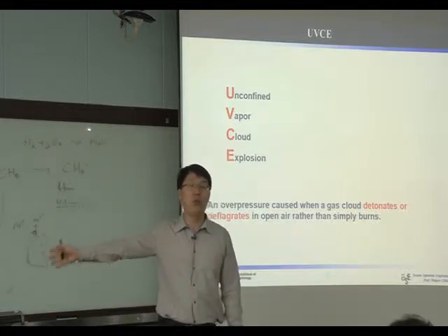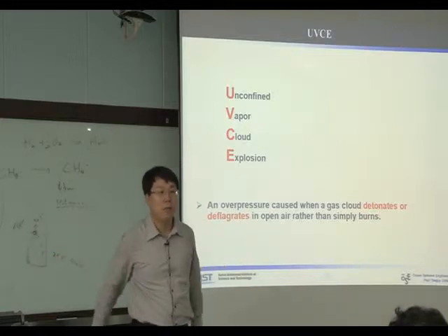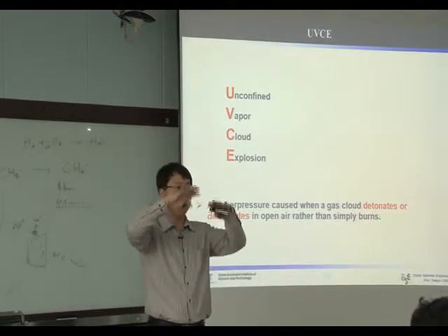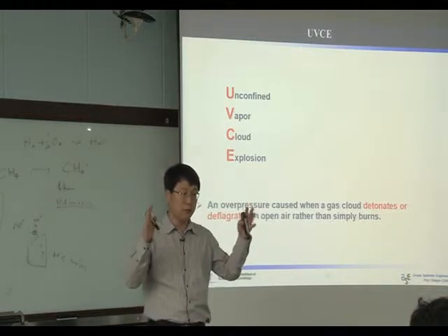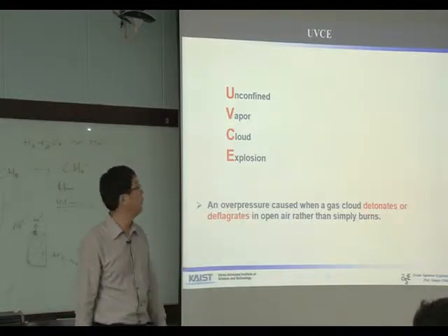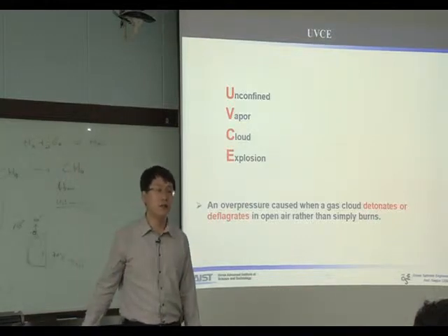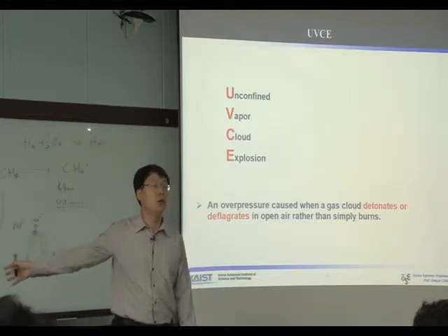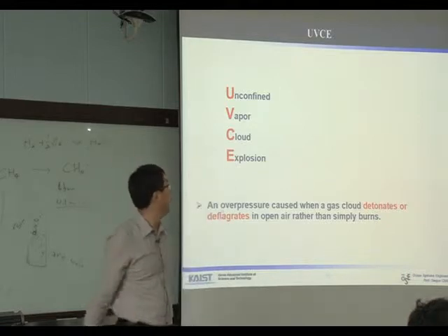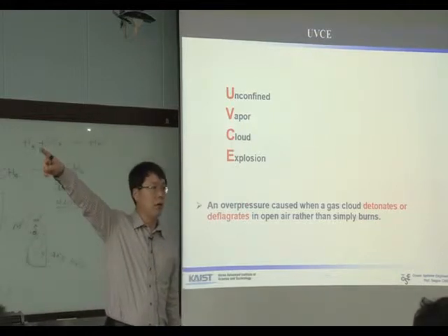If we don't have any walls here, but we have a floor and this ceiling, and we have the explosion here, then this explosion is also confined explosion. Okay, so typically the offshore installation has this kind of structure. That we have no walls around, but we have a floor and we have a ceiling. So unconfined means explosion over there, okay, open space.